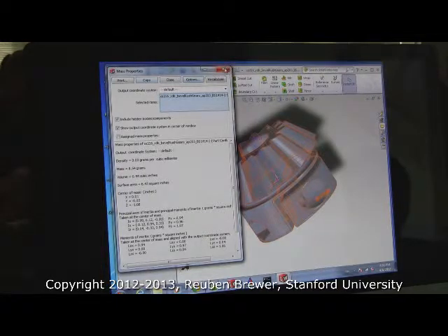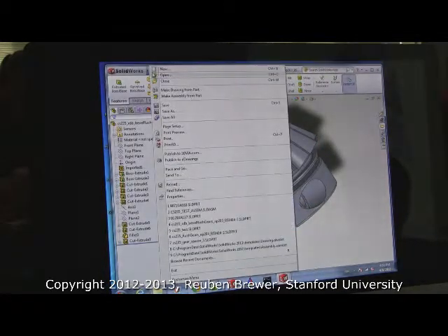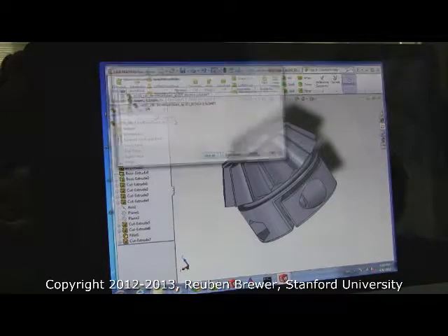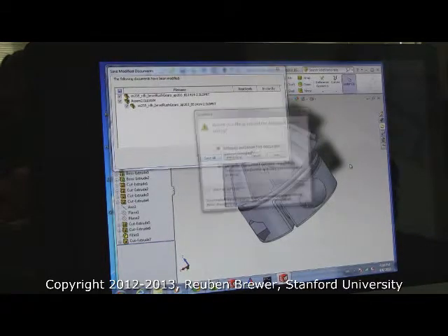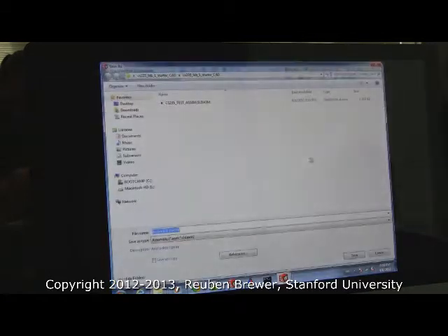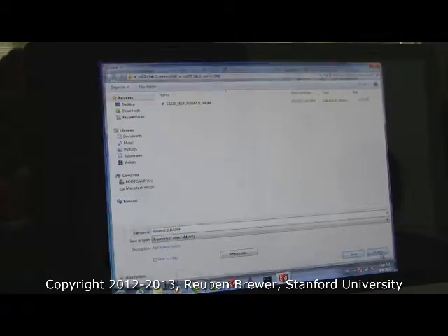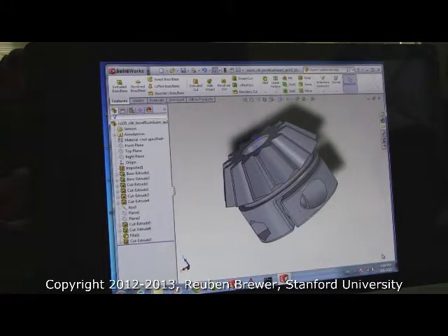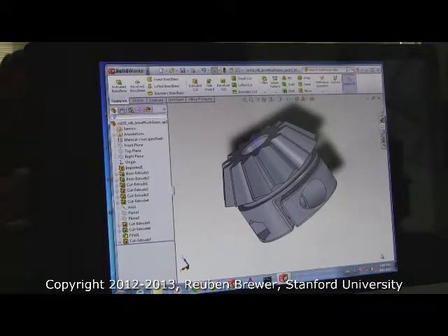And why this is useful is later on, there are 2 reasons. It will tell you whether or not you need a forklift for your robot. That's funny, but my robot, it's a 15-degree freedom medical robot. It's meant to be in a hospital. I actually had to get a special order pallet jack just for installing it in places. The other thing is if you have counterbalances that are based on gravity and gravity bobs, this is how you determine how big that gravity bob is and where it goes.